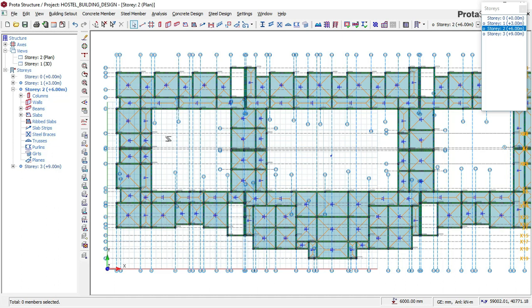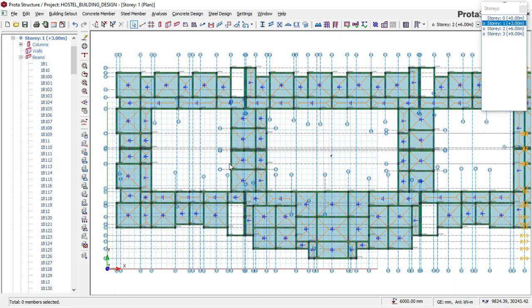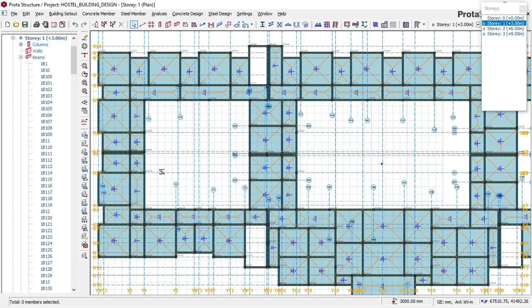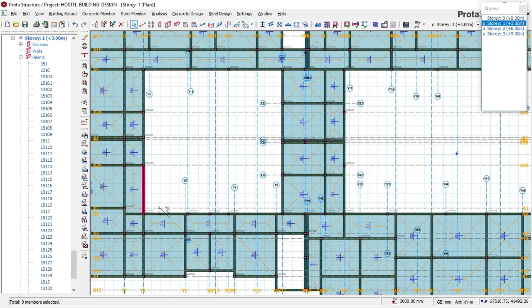Sorry, we said we are going to remove the wall load on the perimeter area. So I'll first remove the wall load on story 1 on the perimeter beams of this courtyard. Let me zoom in, click on all the perimeter beams around the courtyard here, and delete their wall loads, not the beam, but the wall load on the beam, because what is found in this area are steel rails, like iron steel rails, pipe rails and steel pipes.